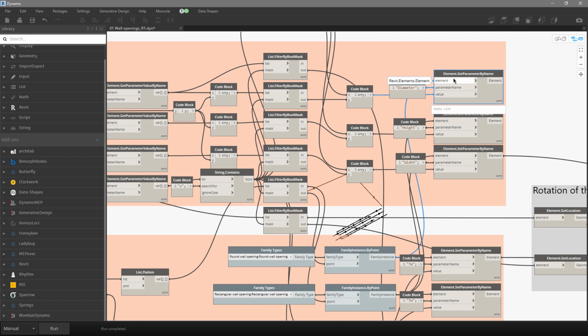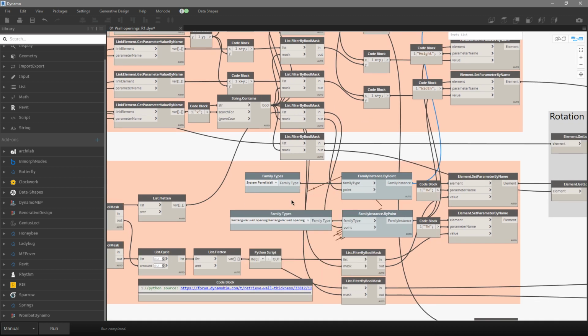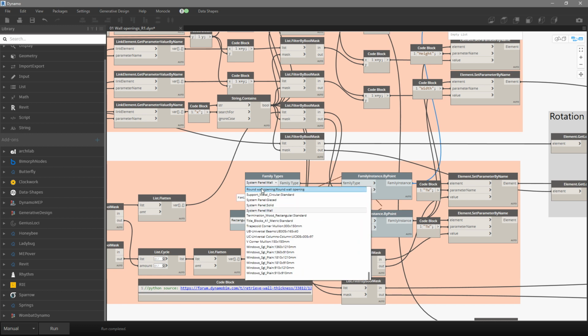So over here we have an element, parameter name, value. Either it is the parameter name, like in this case, where the Russian version of Revit does not have the parameter name diameter, or it can be a value. It can be that somewhere along the way something is not correct and this node actually cannot write the value, or there is some problem with this node over here. So maybe over here you selected by mistake some other family and Revit cannot load that, or sometimes over here it can be blank. Revit just cannot find the family which you require and it cannot load it.